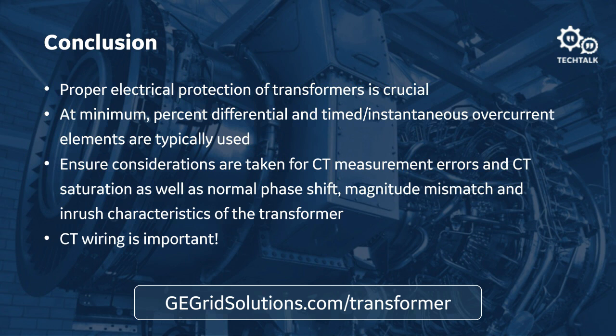A question related to the grounding again. If both my windings are Y grounded, do I still have to set the grounding to within zone? Yes, you do. Sometimes it's assumed that because there is a ground on both sides, this provides a path for the zero sequence current to flow both in and out of the zone, so it won't affect the differential.